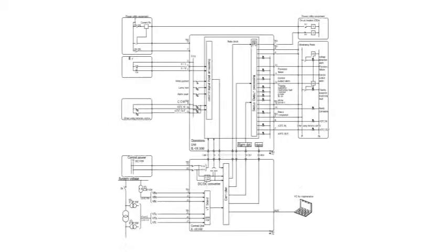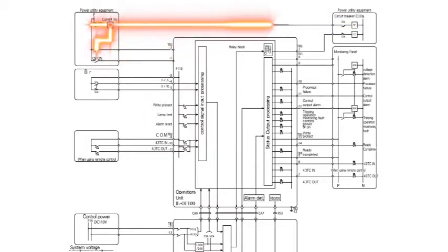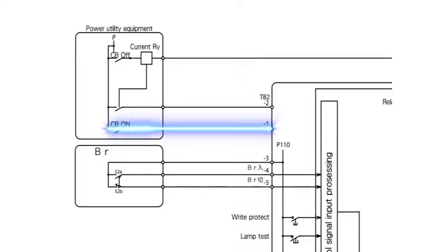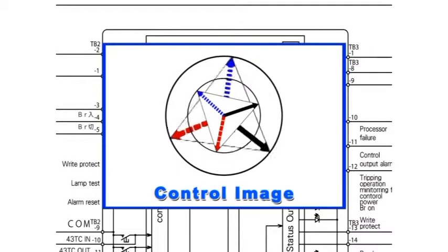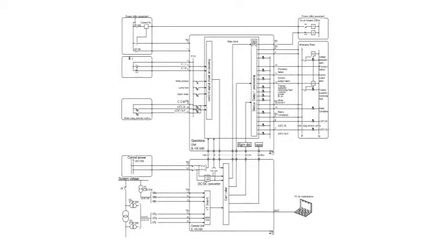To allow the T1 to control the circuit breaker, input the trip signal of the circuit breaker through a current relay. The T1 only references this signal and never interferes with the tripping operation. Input the circuit breaker close signal. To allow the processor to determine the proper timing, the T1 acts as the interface for outputting the close signal to the circuit breaker. Essentially, the T1 is spliced into the circuit breaker close signal line.